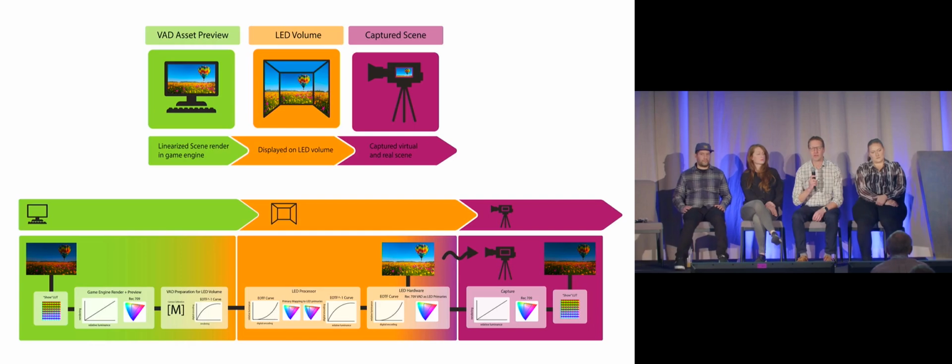Clearly, if you get into higher end visual effects where people know their color and have color scientists, you play with bigger spaces, you try to not restrict yourself. But for today's representation, it's a common language I think we can all understand. The color processor, the LED processor, is responsible for acknowledging that no LED emitter is a Rec. 709 color set. The primaries are not the same. And so, of course, you've got to relinearize that signal that the game engine sent you, and you've got to be able to turn your primaries from Rec. 709 encoding into the actual drive for the processor.